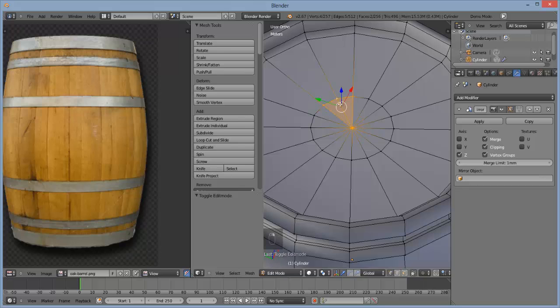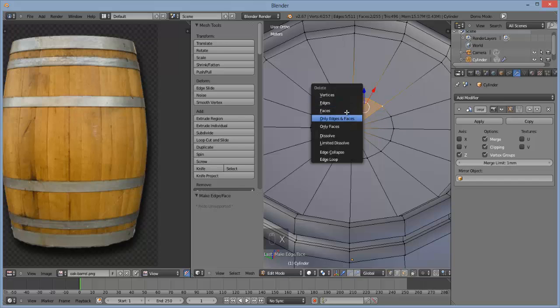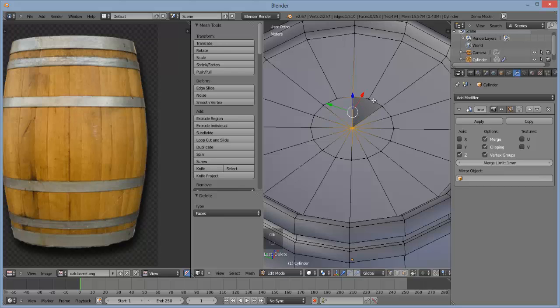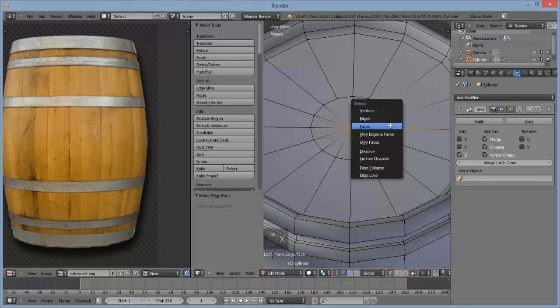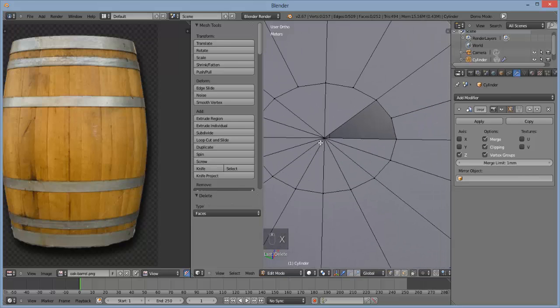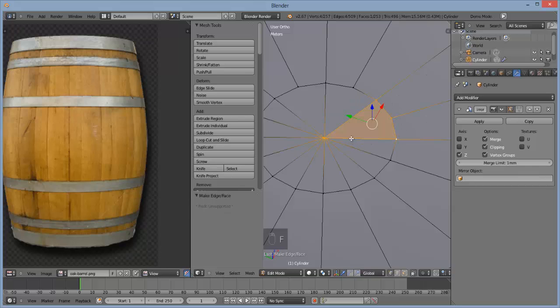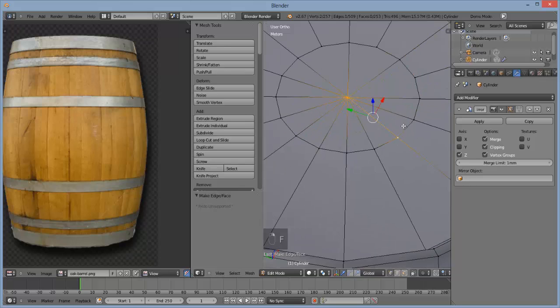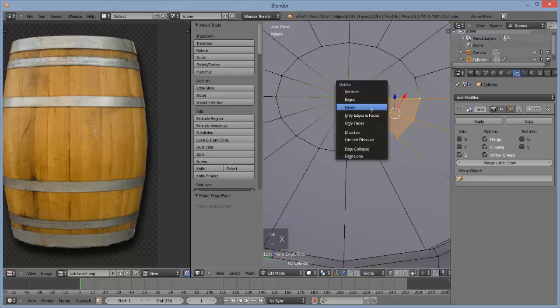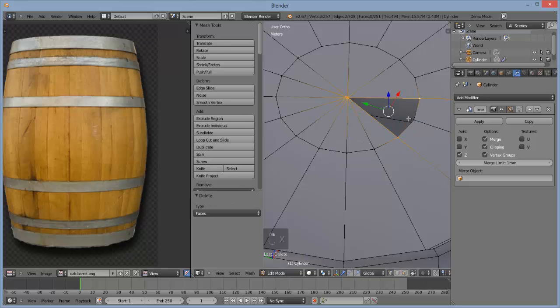get rid of the triangles. So I'm going to delete them and replace them with quads, just because I find quads to give you better geometry, especially during rendering. So I'm just deleting this by selecting two sets of triangles, then pressing X to delete, and then selecting the vertices and pressing F to fill in a face in between the 4 vertices, creating a quad.